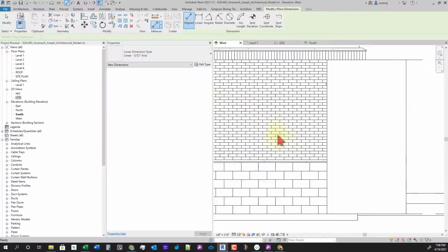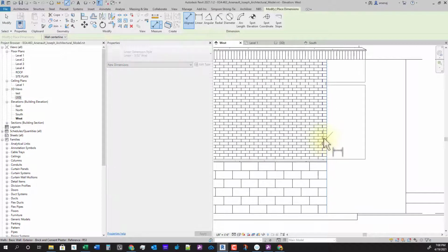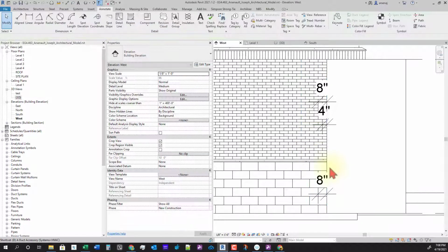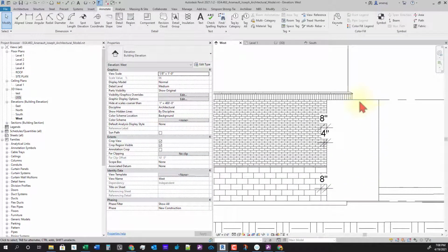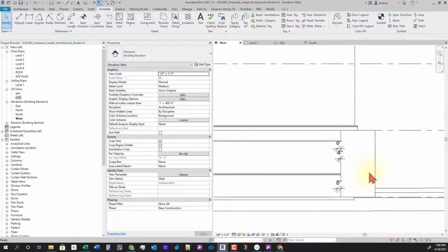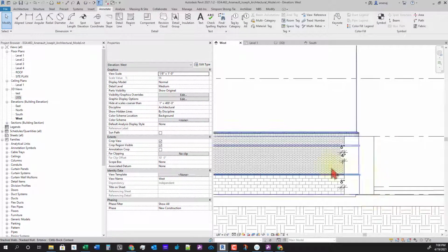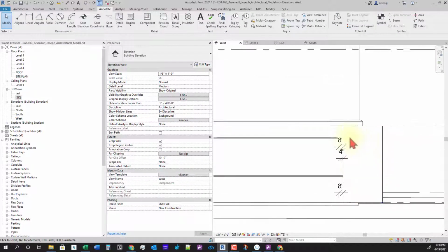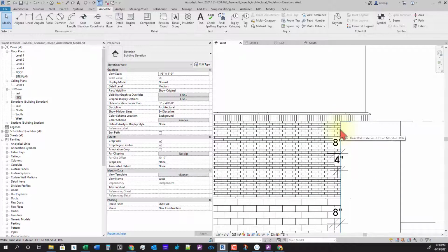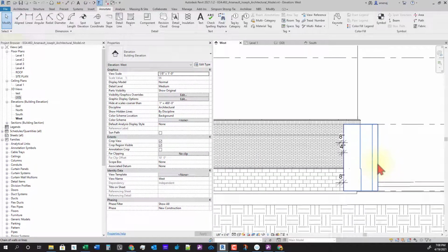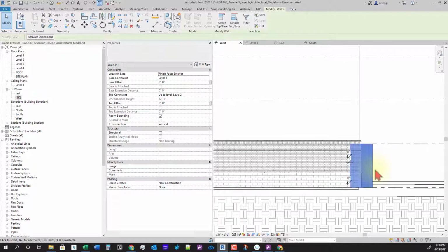Let's check our west side to make sure that that's the same. 4 inches and 8 inches, 8 inches, and 1.4. So in a way, if we add this third wall here, we can fix the masonry layout without having to change the coursing layout or do much work.